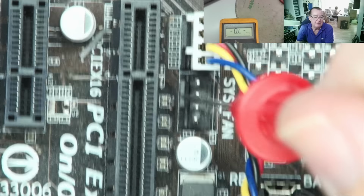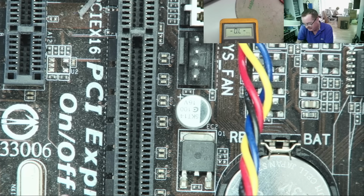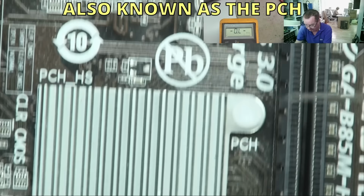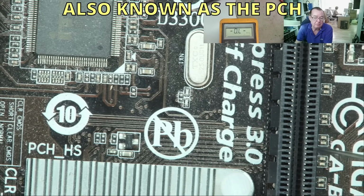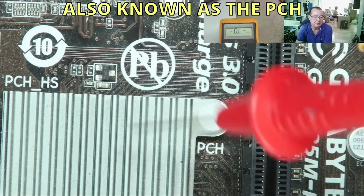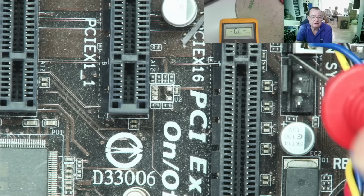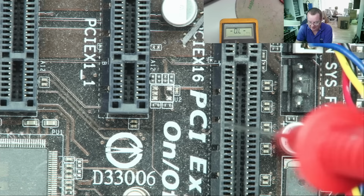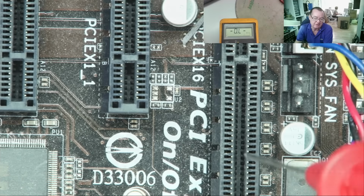Where these lanes go to on the motherboard will depend on the type of processor, basically. If it has an inbuilt memory controller, if it has inbuilt PCIe lanes, or it may go to the North Bridge. On this chipset, it looks like the North Bridge. Yep, you can see they all go there and under here, so you can see that's where they go to on this one. The main point of this, though, is that both sets of the wires, the 4 wires making each lane, actually all have capacitors in them.